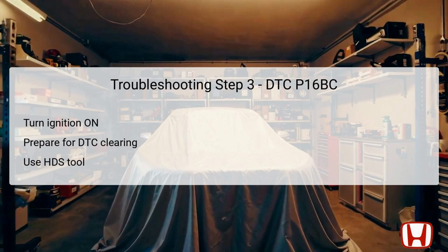Turning the ignition switch to the ON position is crucial for subsequent steps in troubleshooting. At this moment, the vehicle's electrical system is activated without starting the engine, which allows for diagnostic tools, such as the HDS, Honda Diagnostic System, to interface with the vehicle's onboard computer systems.